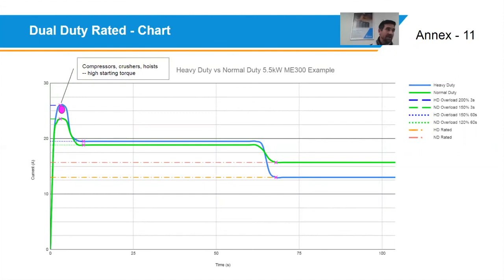If you wanted to go SCADA directly to drives and directly to PLCs, it's also possible. If your PC has a serial port, you could COM directly to the drives over serial, or alternatively add Ethernet cards to your variable speed drives, and then have your SCADA talk directly to each drive over IP and talk to the PLCs over IP as well.